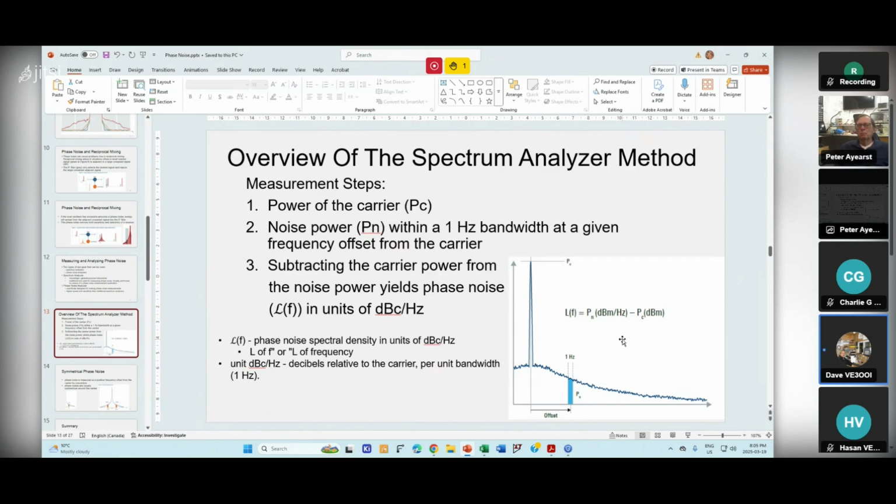Let's just say it's the same. Because the noise is spread out across all frequencies, you have to look at the density of noise. You take a sample and say, in 1 hertz, how much is my noise? So if I have 10 kilohertz, I'm going to have 10,000 times the noise of 1 hertz.